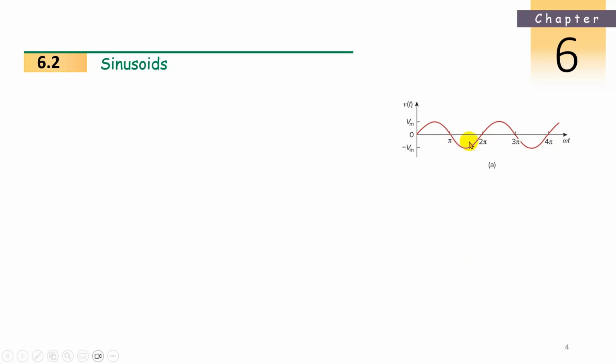Correct. Now at this point, let us take the exact point where Vm is maximum, 90 degrees, right? Pi by 2. So Vm sine 90 degrees. What is sine 90 degrees? 1. So Vm multiplied by 1 is Vm. So the maximum is Vm. Like this we are proving that our equation is correct. What is the equation? Voltage Vm multiplied by sine omega t.